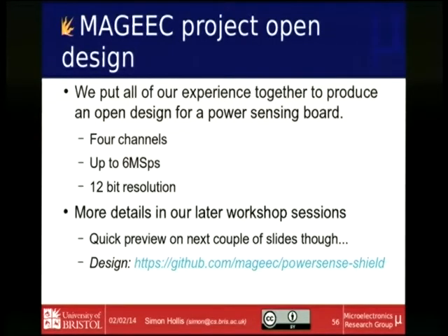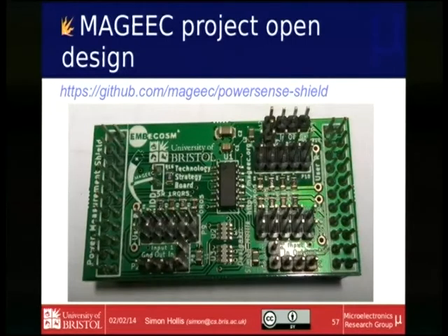12 bits resolution, and this is what it looks like. If you zoom into this in my hand, this is the amplifier in the middle, the biggest part of the device. We've got a big selection of different shunt resistors that you can insert by connecting to the board. So you have to do some soldering. All you have to do is connect your power supplies into some pins here. So you have to break the power supply trace on the board, take 2 wires out, and push them into here, here, and here, and then that's it. Then you set some jumpers, little nice red jumpers we've got, and this will then do all of what I've done. It's designed to be carefully controlled.